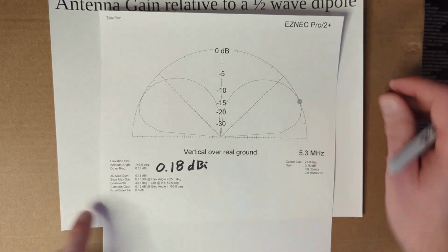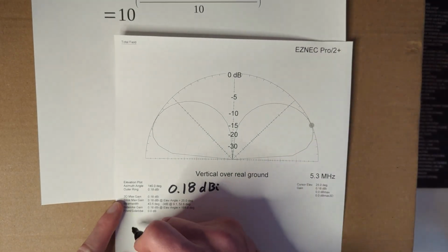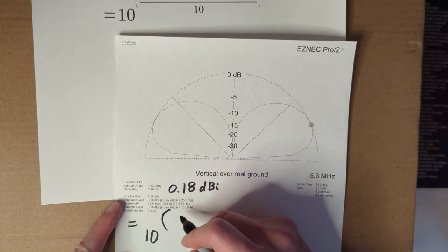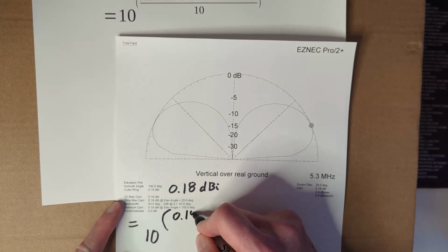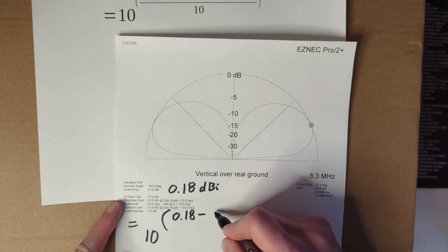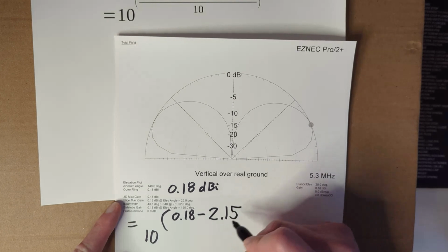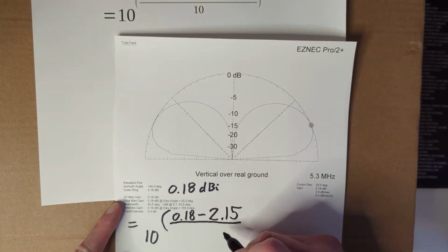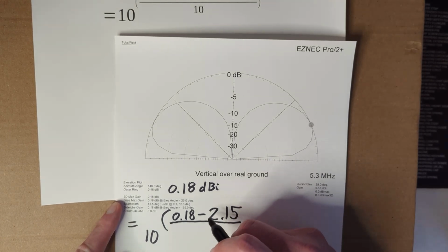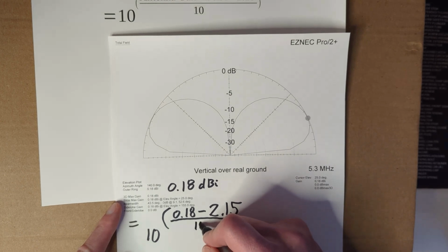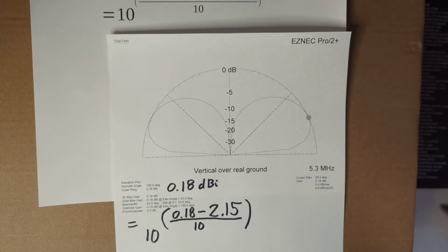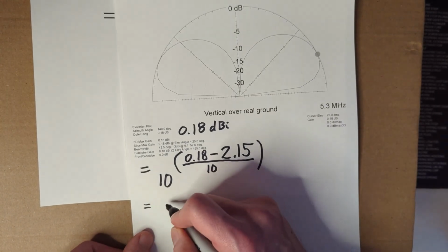So that would be 10 to the 0.18. We're filling that in from here, what the software calculated as the gain. Subtract 2.15, and what that subtraction of 2.15 does is convert this from decibels relative to an isotropic radiator to decibels relative to a dipole. And then the rest of this equation is converting decibels into just unitless gain. So going through this,